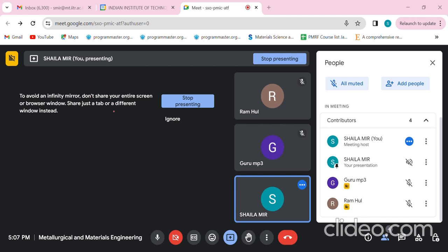You see, this is the solidus line. This solidus line is actually a phase boundary between two phases, which is alpha plus liquid and, for example, alpha. While this solvus line is a boundary between your alpha and alpha plus beta. So this is the solvus line. So you can see this is the right option for alpha and alpha plus beta.